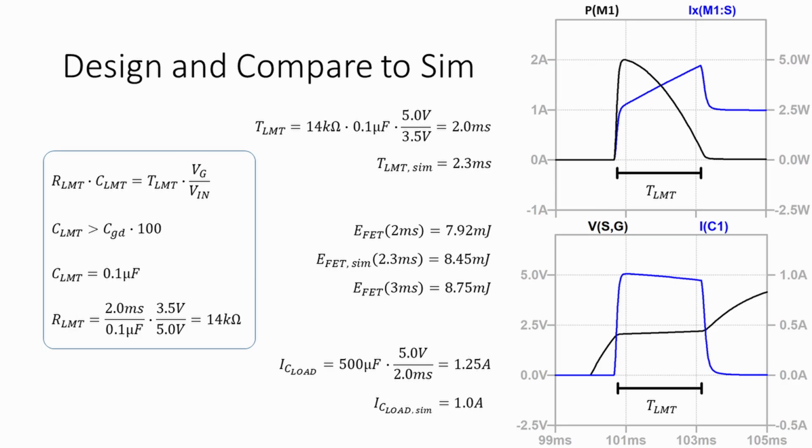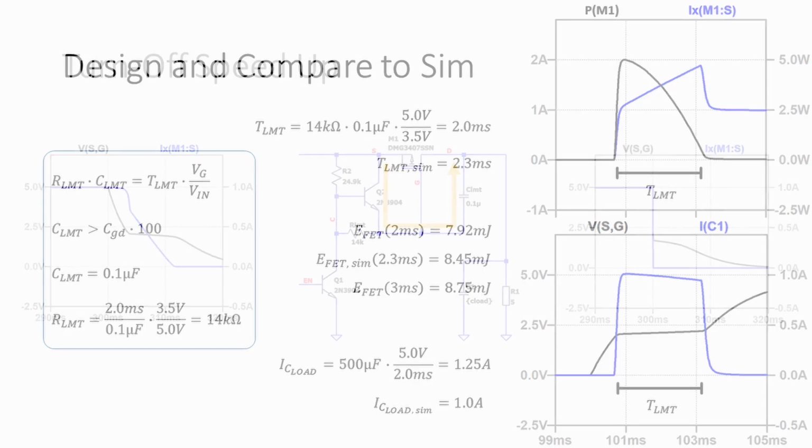There's not really a reason to adjust this, as variation in the gate voltage should be expected. There will naturally be differences in these values due to part variation, temperature, or other factors. Worst case analysis can be used on something like this to ensure that the part is always safe. If it didn't pass, we'd have to choose a different package or lower the capacitance of the load.